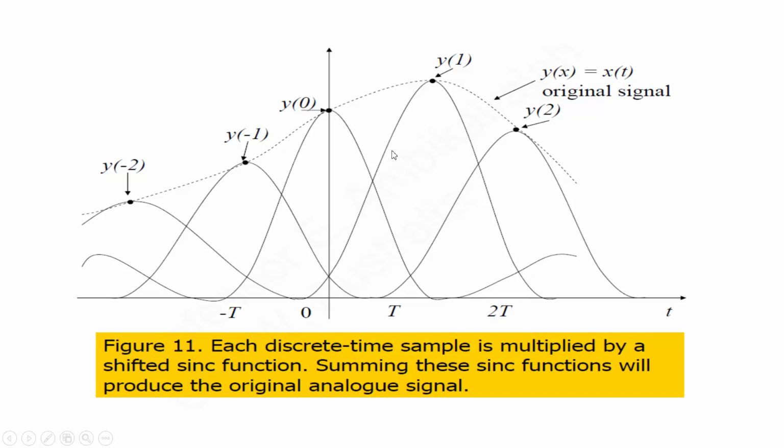There will be multiples of sin x by x, as I said earlier, sinc functions. Each discrete time sample is multiplied by a shifted sinc function. Summing these sinc functions will produce the original analog signal.